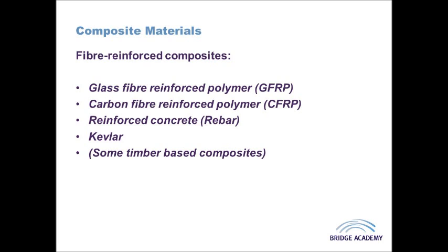Now, quite often we abbreviate these things to glass fibre or carbon fibre, but sometimes it's good to be particularly specific about the wording of these because the exam can be quite critical in this sense. Glass fibre and carbon fibre reinforced plastics are obviously made with a mat or a series of fibres that are kind of woven together. Now, these are then combined with a liquid resin or liquid polymer that creates the matrix that surrounds those fibres and basically holds them in position.